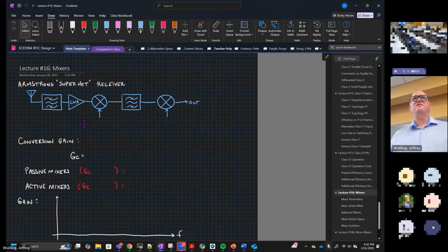Hint, it's just a nonlinearity, or some type of commutation, but some type of nonlinear function that we're going to mix with a linear function and end up getting a lot of different harmonics. So it's a lot like the concept of the Taylor series expansion we did when we were looking at intermod products before. In fact, that's the first mixer we'll look at, an intermod based mixer.